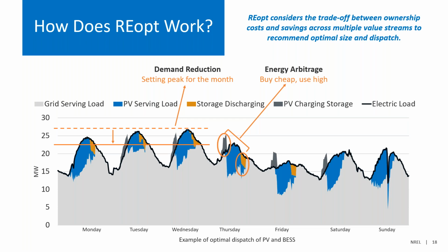And just as a note, REopt and SAM in this case are solving similar problems. REopt is doing this via an optimization, which constrains the equations that they're able to use a little bit into non-convex equations, but then it does spit out that optimal size. Whereas in SAM, we have greater flexibility in the equations that we're able to model. So for example, we can use a detailed voltage model in the battery as opposed to a flat efficiency, but then you have to rely on tools like REopt or parametrics in order to size systems.